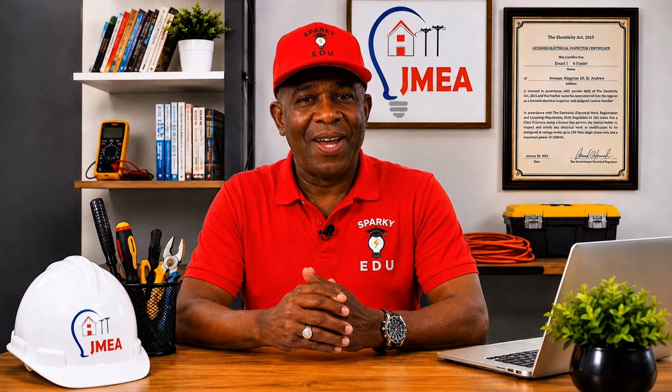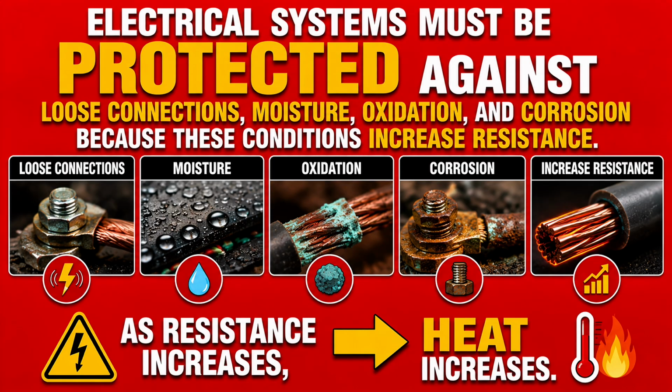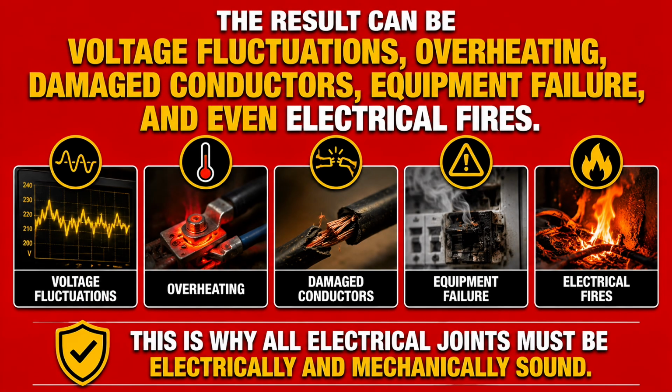Now let's connect this chemistry to electrical installations. Electrical systems must be protected against loose connections, moisture, oxidation, and corrosion, because these conditions increase resistance. As resistance increases, heat increases. The result can be voltage fluctuations, overheating, damaged conductors, equipment failure, and even electrical fires. This is why all electrical joints must be electrically and mechanically sound.